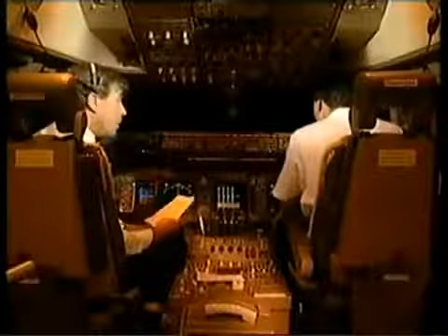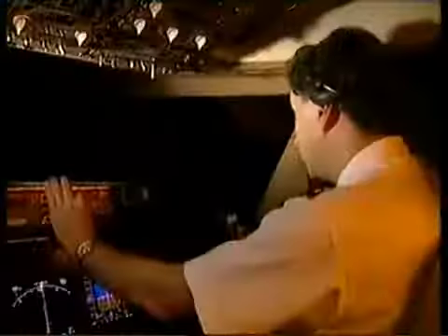I have control. We've been assigned runway 16 right, so I'll brief for that. Sydney runway 16 right, ILS PRM approach. Category 1 minimum, 220 feet. 220 set. Visibility, 800 metres.